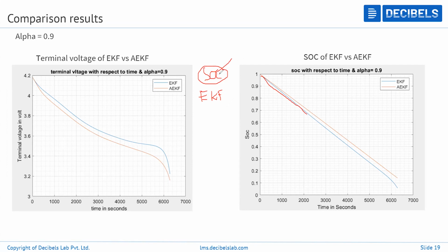It again depends on how much sensor data you are going to believe. For example, if you take the EKF based SOC estimation, you are going to feed the voltage value and current value. So how accurate these are, right? With that, you can compare your results.